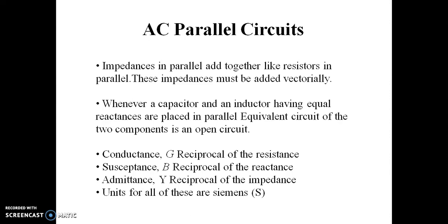AC parallel circuits. Impedances in parallel add together like resistors in parallel. These impedances must be added vectorially. Whenever a capacitor and an inductor having equal reactances are placed in parallel, the equivalent circuit of the two components is an open circuit.